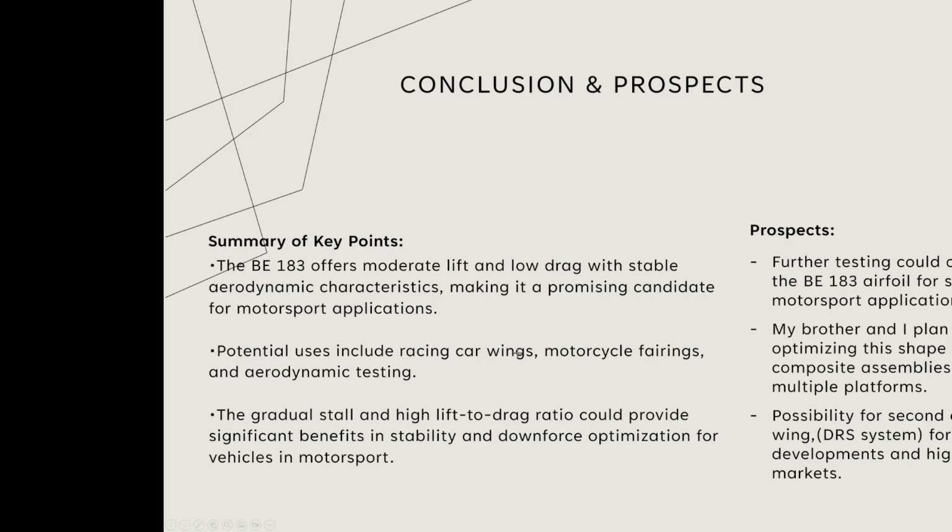You could also do a mid wing with it, but the mid wings are a little confusing just because it's hard to judge what type of air you'll have there, as in if it'll be clean air or messy air, meaning disrupted by the flow of your car moving through the air, versus it being the first thing of your car touching the air. This kind of just restates that first point.